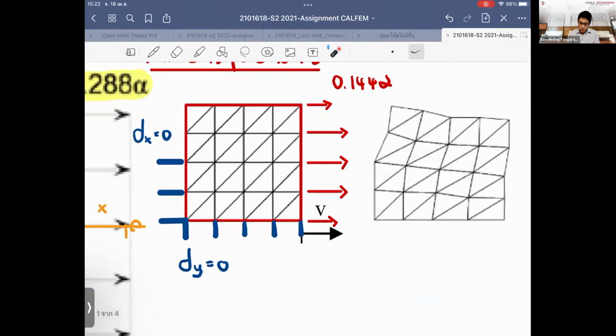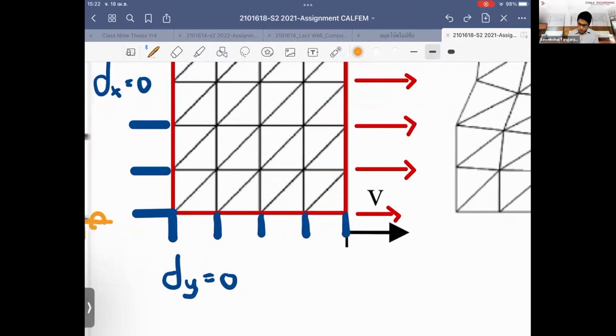The last thing is you just need to discretize the problem. How we discretize a problem is that first of all, you have to allocate a node. I start to discretize, so I start to split the whole mass that we're looking at. I allocate the boundary already. I split the whole mass and I start to assign the number of the node. I start to assign the number of the element and the connectivity of the member, right? So what we do, I just take the node first. This is all the node we're looking at.